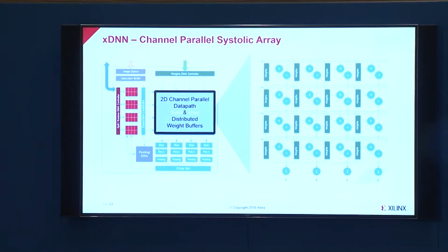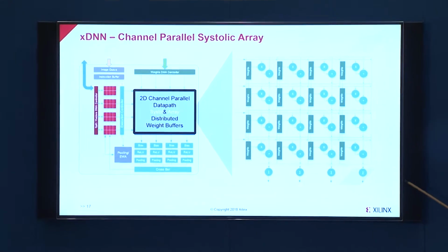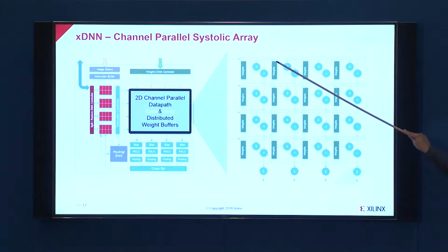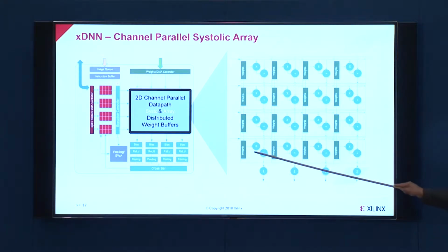So this is the systolic array in this particular architecture. This is our generation 3. You can see that we have used this addition, like a dot product. The data moves here as well as down. Actually, on the chip, the data moves up. And then you do dot products and you do accumulation. These weights are stored in the local RAM, those 64 times 16-bit, 2 of them which are there.